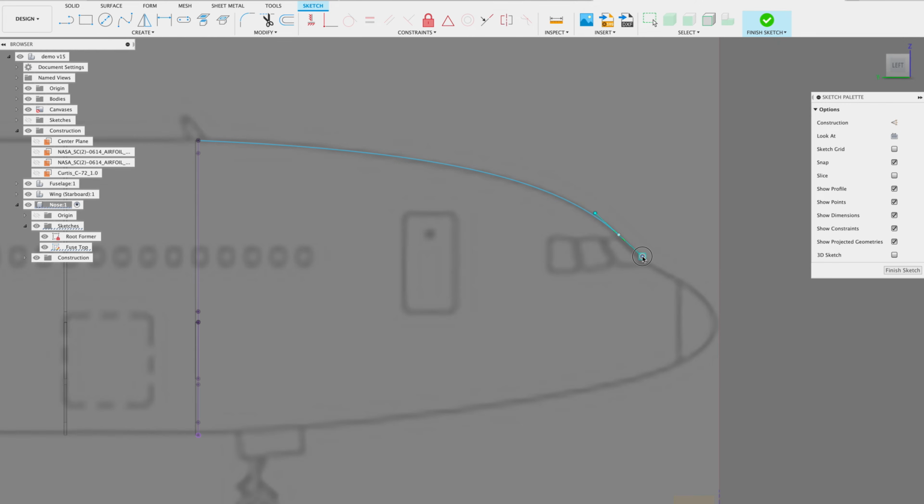And so we're going to match this shape like so. Now you'll notice that I am making the rubber band portion align to the edge of the window. The reason that I'm doing it this way is because when I make my next spline from this point to cover the window, I will make sure that this curvature is as close as possible to being parallel to that window. So I'm going to select that.